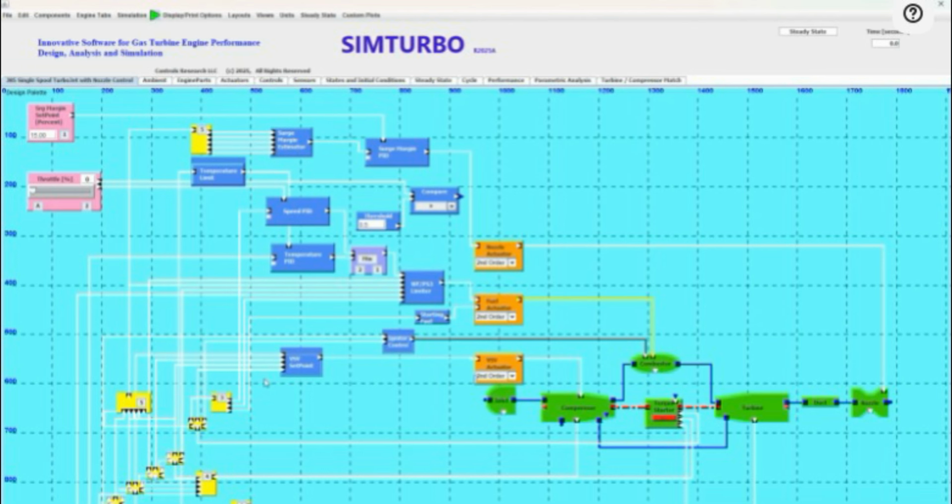The green components are the engine components. The ambient air enters the engine through the inlet component. The ambient conditions are represented by the small blue dot attached to the inlet. The engine inlet guides air into the engine's compressor while optimizing pressure and minimizing energy loss. Note the airflow lines are represented by the blue lines attached between the components. The compressor pressurizes the air to the highest pressure of the engine.